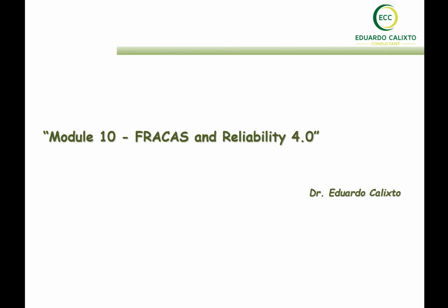In addition, we will demonstrate the relation between the FRACAS, whose main objective is to collect historical data about physical asset failures, as well as corrective actions, and the reliability prediction based on the history of failures. The new solution being proposed here is that the reliability prediction is performed automatically as soon as we start to input data in the FRACAS. We will explain that later on.